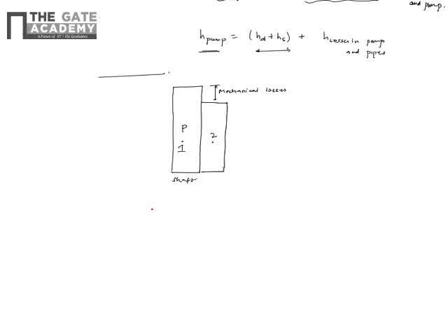Now the output of the impeller, this is what we are tracking. Shaft output is P. We are tracking outputs only, and the impeller output is basically the head delivered. The head delivered, that is H, which is VW, I'm just writing the tangential component, by G. So this is the head delivered by the pump.